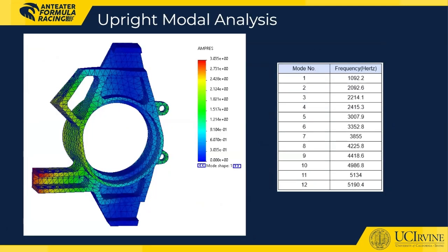For the vibrations, I completed a modal analysis to determine the resonant frequencies for the component, and I found that the resonant frequencies are much higher than those it will experience, so it is unlikely to be an issue.